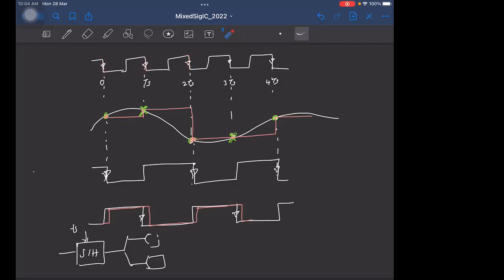So even if there are any delays in the sampling clocks, that is delays of these two clocks, instead of sampling at this point, say this clock samples with a slight offset here, it is still okay because you're essentially sampling at this instant, and the signal at this instant is same as this one, right? Is that clear?